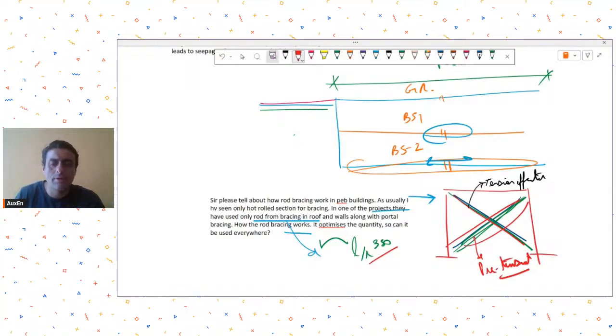However, in my opinion, these types of bars that they provide, rod bracings, they often don't even pre-tension it, so it's a risky proposition, because there is a sag because of the self weight. Now what will happen when lateral load comes? First, a lot of the lateral load will be spent in tightening or straightening of the bar and removing its sag, isn't it?